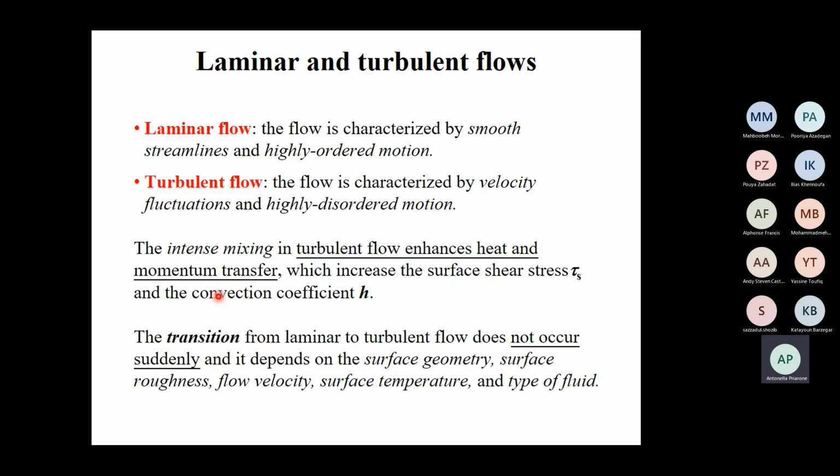That is why I remind you that when I speak about the behavior in heat transfer, I have to keep in mind the behavior from the point of view of pressure drop, because increasing the mixing, entering the turbulent flow, I enhance the transfer rate, but I increase also the pressure drop.